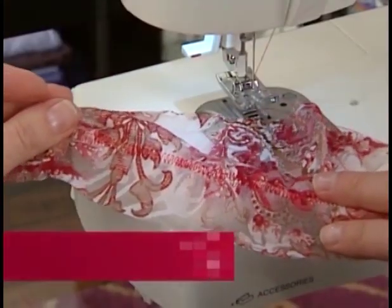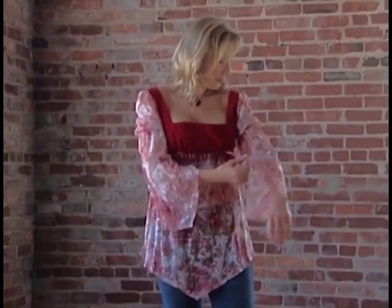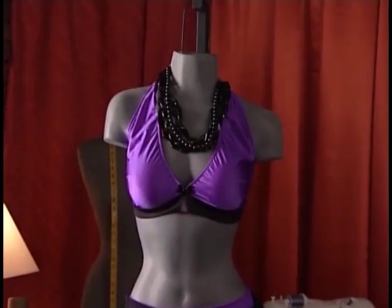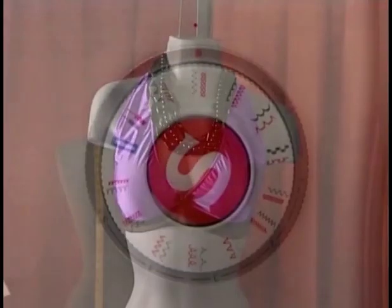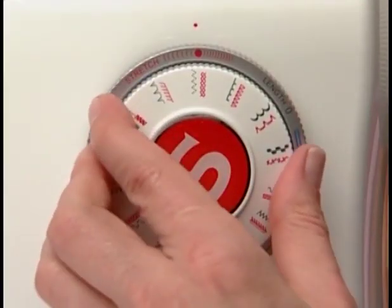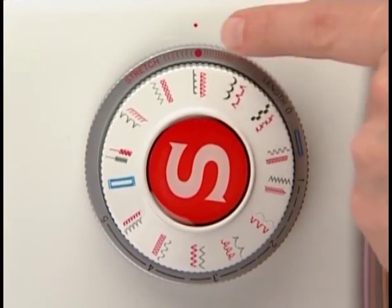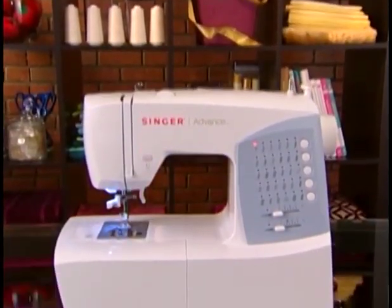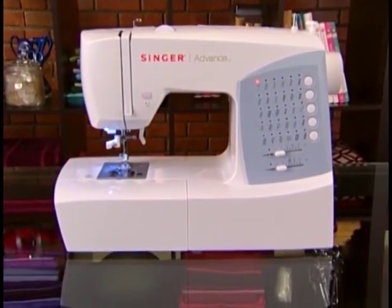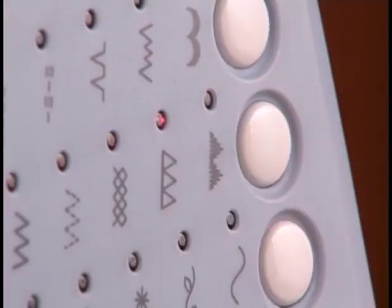Most machines have a selection of stretch stitches. These stitches are mainly used to sew fabrics with an elastic quality like those used to make activewear and swimwear. Most mechanical machines with stretch stitches require you to set a lever or dial to the stretch stitch mode in order to select the stretch pattern. Electronic or computerized machines automatically set the stitch for stretch sewing when the stretch stitch is selected. Let's take a closer look at a couple of these stretch stitches.